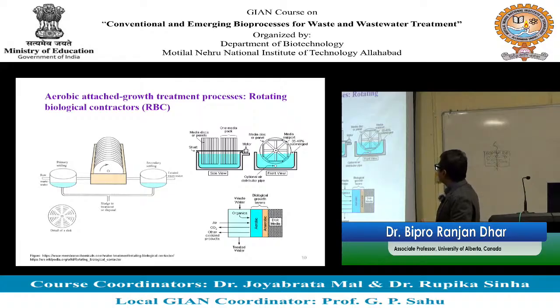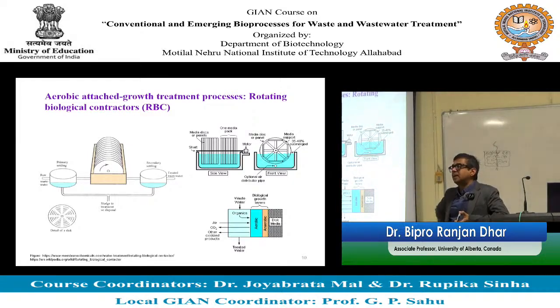And microbes are going to form biofilm on the media panel, the rotating media panel. And this is a biofilm process. A biofilm process is a little bit more complex than a suspended growth process. This is an aerobic treatment process, but still the inner film of biofilm in your media can be anaerobic. Why is that? Depending on how much dissolved oxygen level you have, there may not be enough diffusion in the inner layer of the biofilm.